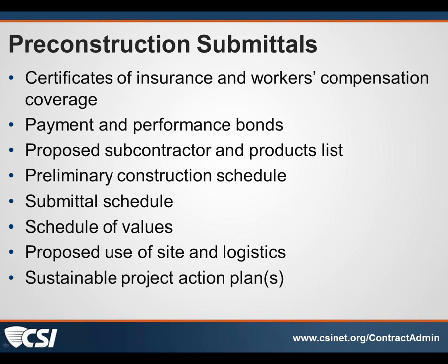They're all critical to the schedule, and they're all critical to our delivering this project on time. And if you can't get them back to us, and guess what? The specification that we were working with, we ourselves said we would return the submittals in 21 days, or some arbitrary number that someone had put into the specifications as a turnaround. Now, I'll just stop and say, if you're staffed such that you can reply to everything in the time frame that you say in your specifications, great. If you can't, take it out. Don't leave that in there.